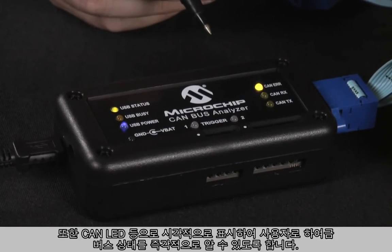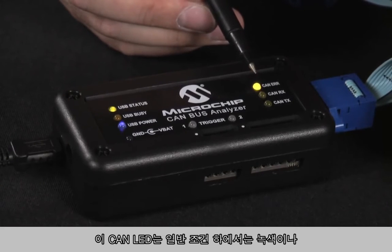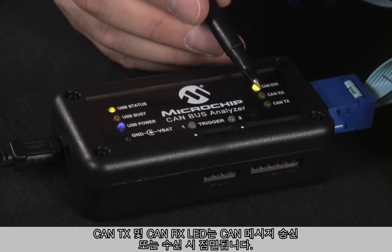The tool also provides some visual indications to give a user a quick view of the bus status, such as the CAN error LED. This CAN error LED shows green under normal error conditions, or turns yellow under error passive conditions, or red in CAN BUS off. And the CAN TX and CAN RX LEDs will flash when CAN messages are transmitted or received.